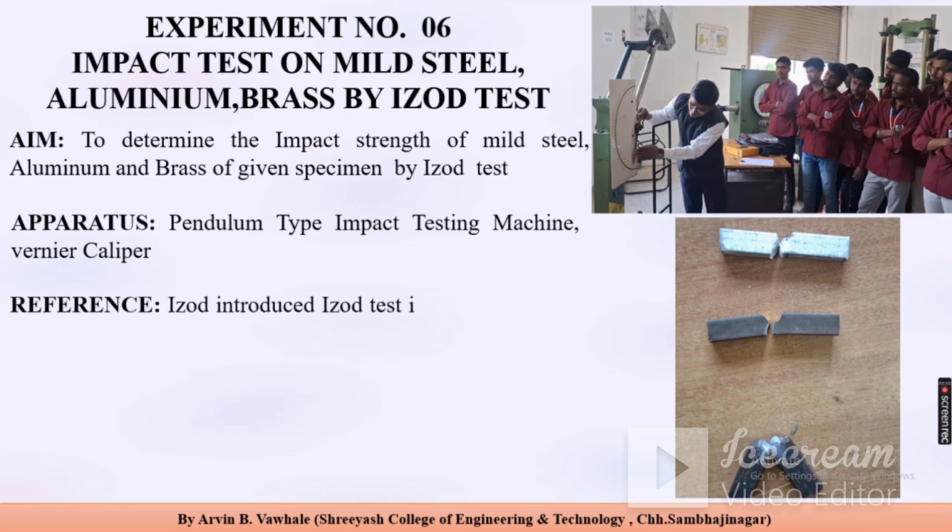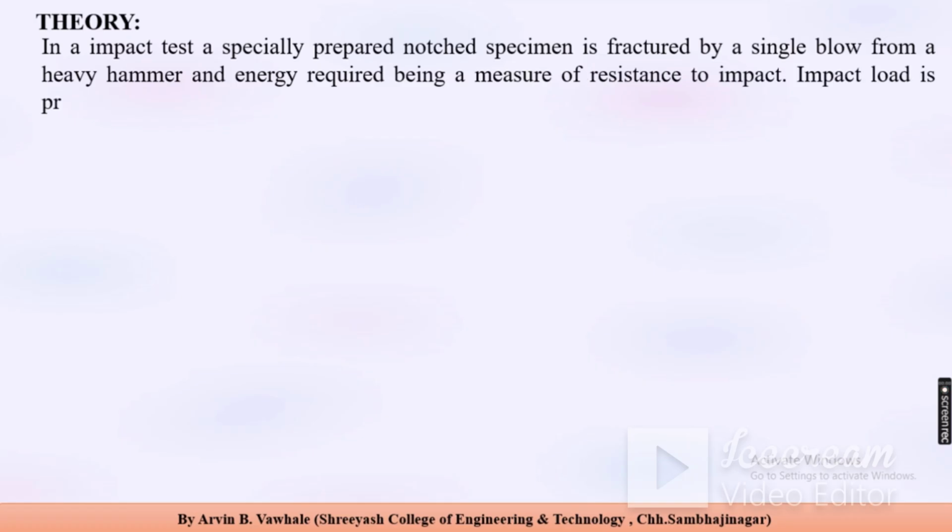Reference: IZOD introduced the IZOD test in 1903. The test is as per IS 1598. Theory: in an impact test, a specially prepared notched specimen is fractured by a single blow from a heavy hammer, and the energy required is a measure of resistance to impact.